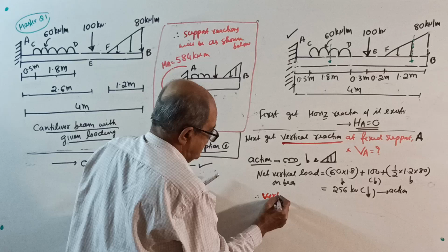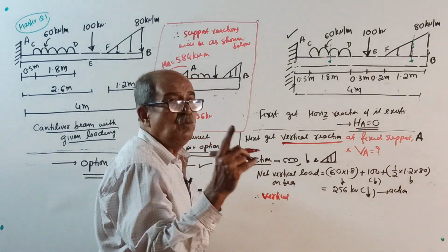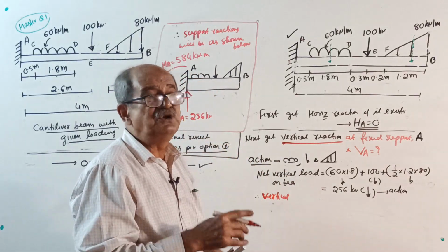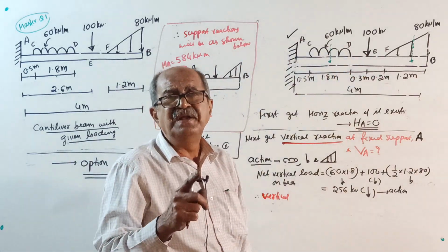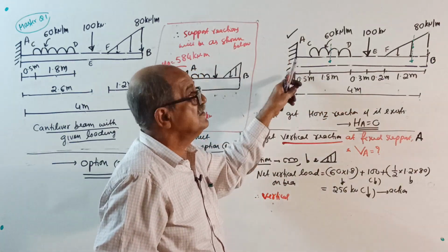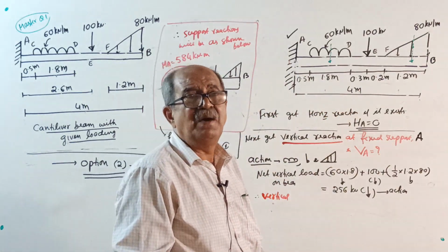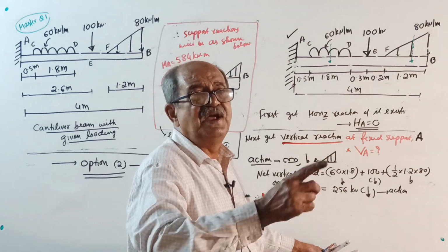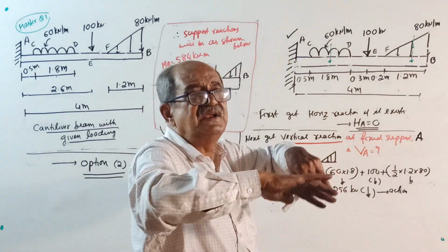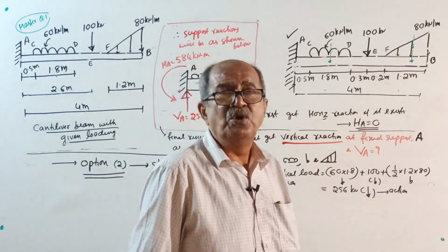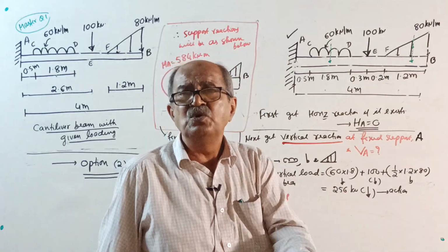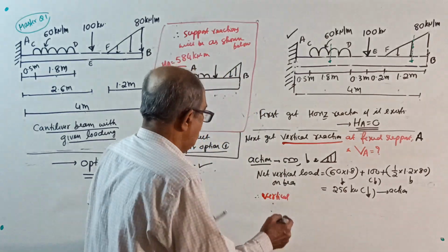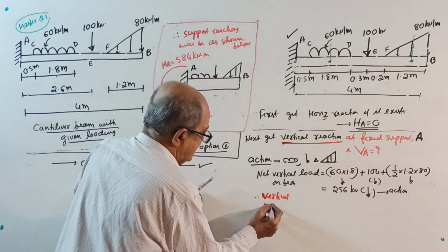Therefore, vertical reaction: there is only one vertical reaction. There is no sharing. Whatever is the loading on the beam, in a cantilever, everything has to come here. If you stand on a slab or floor where both sides beams are there, loads are shared. If you sit in the portico or cantilever, wherever you stand, load will be transferred to the support only.